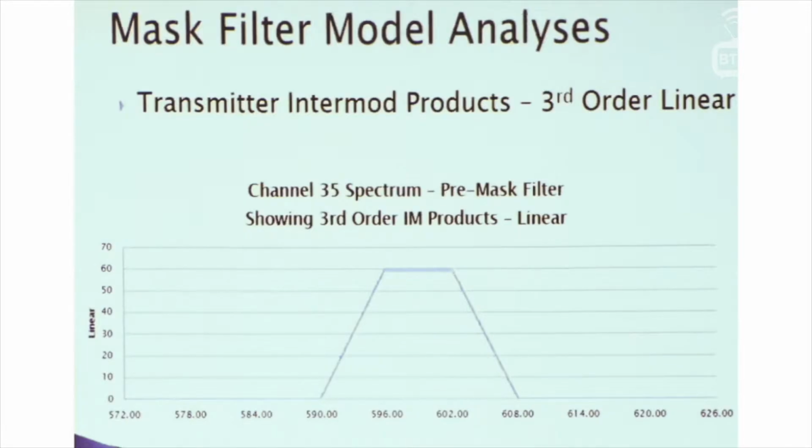And so that's why with digital signals, where we have a broad spectrum of power, we tend to have intermod products that go out in smooth spectra, where when we were doing this with analog signals, you'd just get the individual carriers that would intermodulate with one another. And by seeing where the product ended up, you could tell what components were in it. We don't have that luxury anymore with digital signals. You only need one transmitter to cause intermod, where in the old analog days, you needed multiple transmitters to generate intermod products.